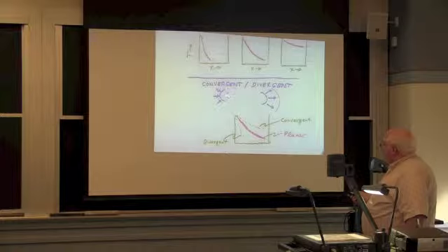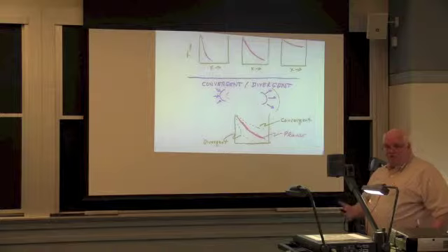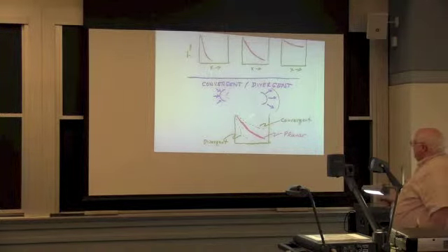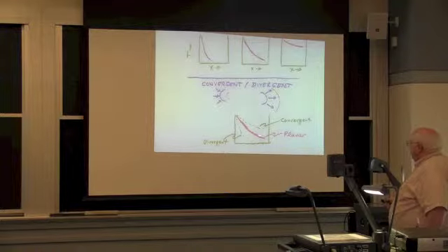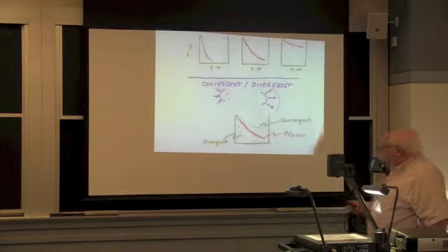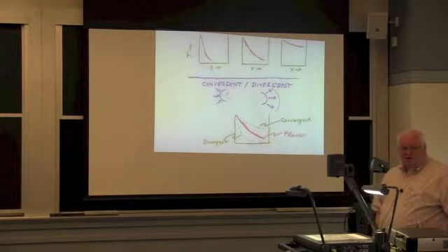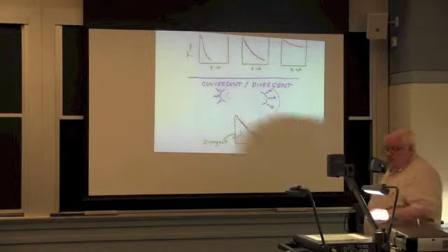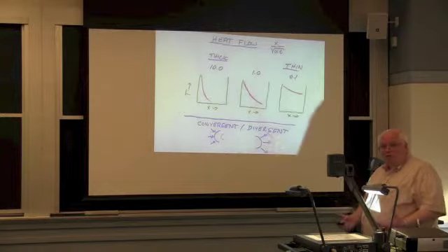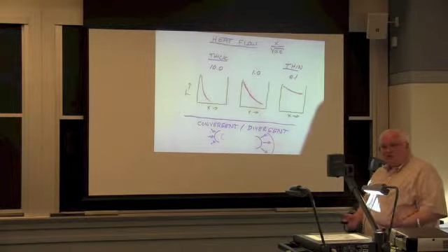Here, the area is decreasing as 1 over r. Here, it's increasing as 1 over r. In a sphere, it's decreasing as 1 over r squared. And here, it's increasing as 1 over r squared. So if you're in a planar situation, you have this, but convergent will be faster heating and divergent will be slower heating. And these are, in most cases, maybe a factor of 2 difference. But in a lot of cases, I don't even care about a factor of 2. I just want to know, did I heat all the way through, or did I barely touch the surface? Okay?